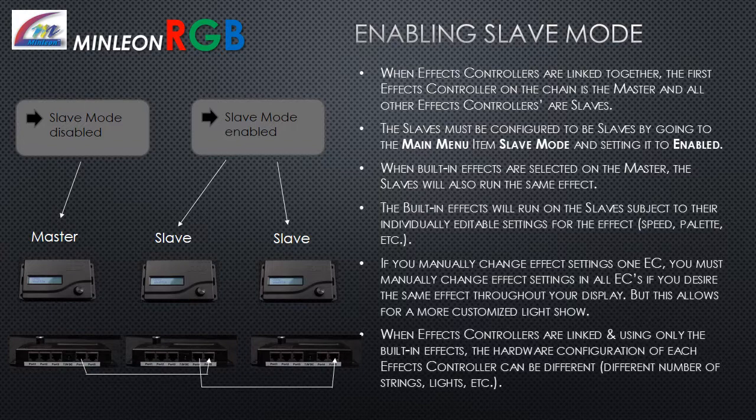If you manually change effect settings on one EC, you must manually change the effect settings in all ECs if you desire the same effect throughout your display. But this also allows for a more customized light show. When effects controllers are linked and using only the built-in effects, the hardware configuration of each effects controller can be different.